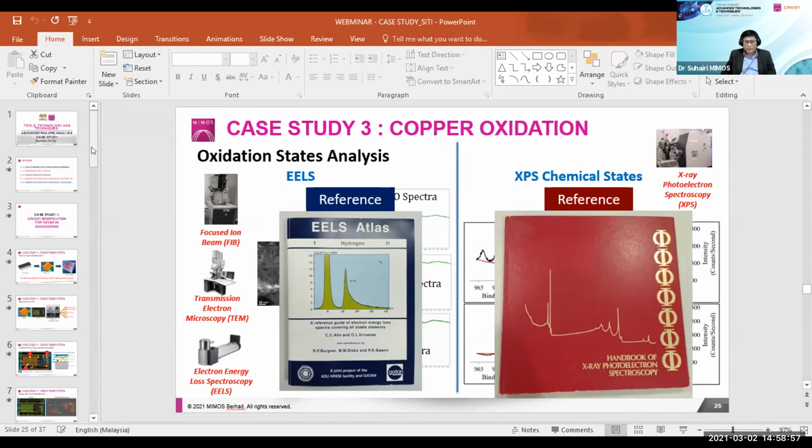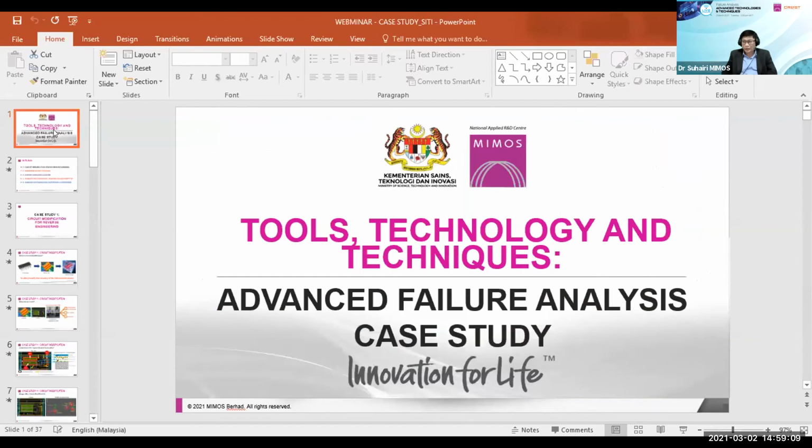All right, hold on, there are a few more questions, but I would like to answer a question from an anonymous attendee regarding how to differentiate ESD and EOS defects. For EOS, you can visibly see the burn mark, but for ESD, it's not as straightforward as that, and you would expect to see some pinholes at the active area. So that's my short answer. Again, I wish that for some of the answers that we cannot answer now, please help us by providing your details so that we can follow up with you.